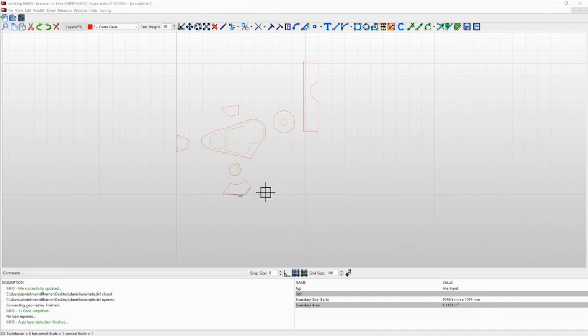So what steps are necessary? Break geometry, offset geometry, set layers, trim and extend with AutoCAD. With NestKing we already have the join function, and finally connect. So we need 5 steps to get this final offset.